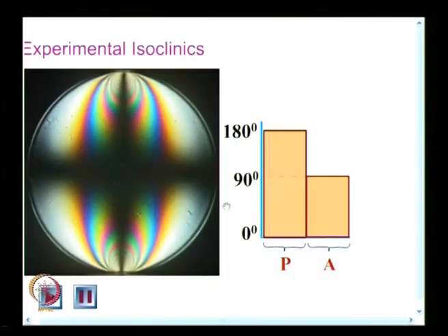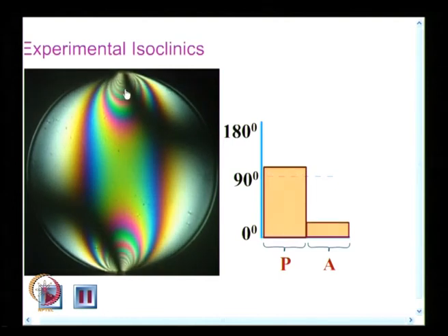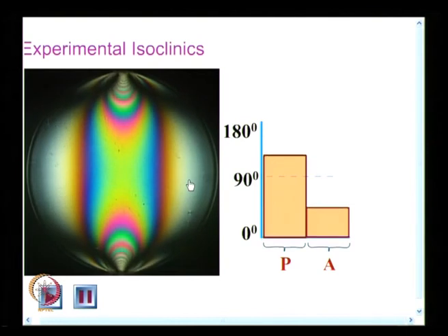You can identify the color band. What do the color bands show? They are contours of sigma 1 minus sigma 2. So, in this optical arrangement I get two pieces of information. One is sigma 1 minus sigma 2, and the other is the orientation of the principal stress plane. If you have two pieces of information superimposed, the clarity is lost. So, you would always like to have independent information, then processing and data collection become much simpler.